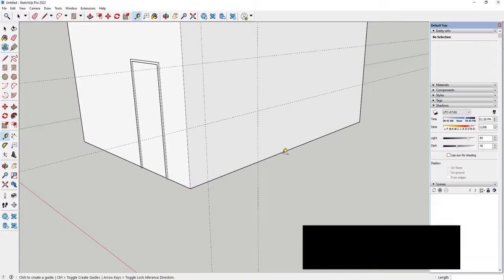So let's go ahead and jump over to our rectangle tool. Now that we have these guidelines, we'll type R. We'll move over to this top corner right here. And as you can see, SketchUp knows we're trying to work off of these guidelines. So let's left click and we'll drag to meet this corner of the guidelines. We'll left click. And just like that, if we move over to the select tool, now that one face has become two faces.